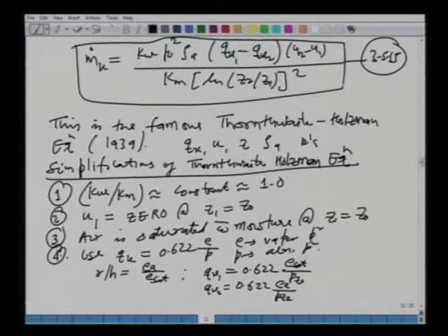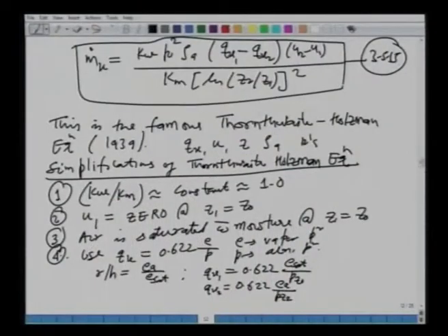What is the change in pressure as you go up at cross section 2? We have this relationship. Once we know the pressure on the ground, we can find out its variation as a function of height. And from here I can say then EA is your relative humidity times ES. We can measure the temperature at a certain height, calculate the saturation vapor pressure corresponding to that temperature, and once we have the relative humidity, we can find out the actual vapor pressure.